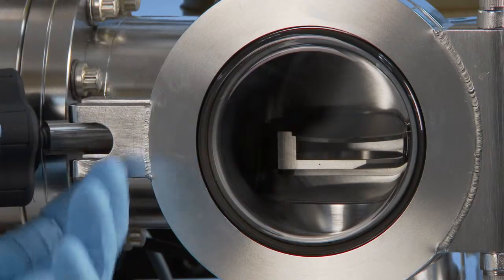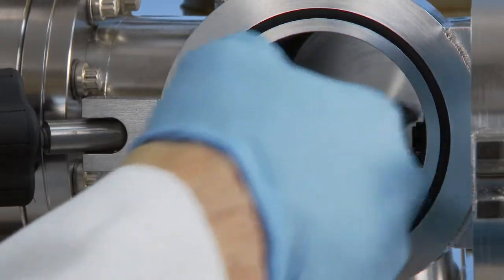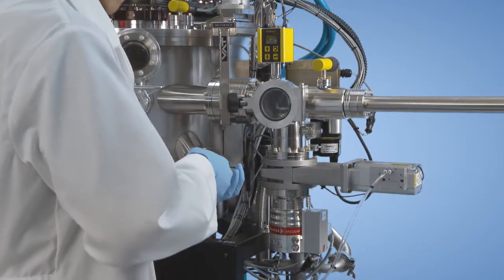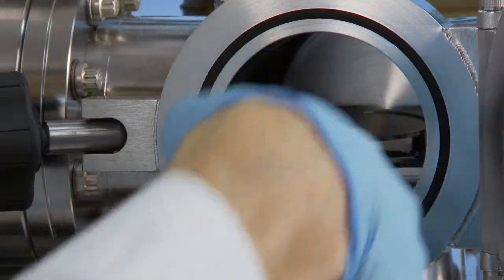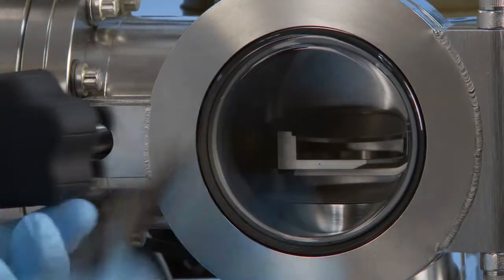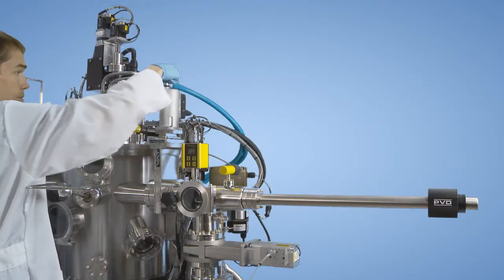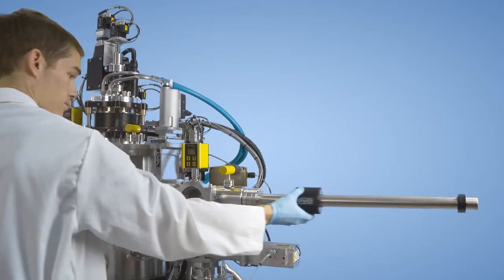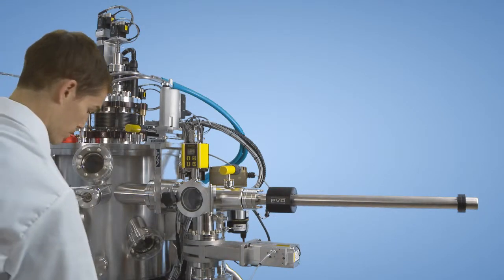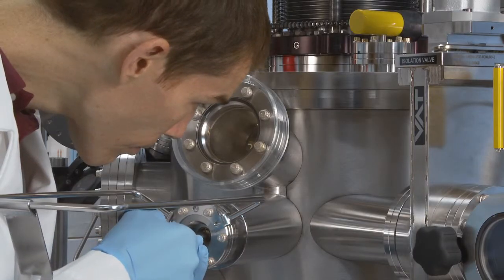Other features include our dual wafer load lock that allows the user to remove an already coated wafer and insert a new wafer into the PLD chamber in only 1 pump down cycle, greatly increasing the efficiency of your investment. Adding this option also reduces the base pressure of the main vacuum chamber to 5 × 10 to the -8 torr. We also offer a bakeout system to achieve pressures in the 5 × 10 to the -9 torr range.